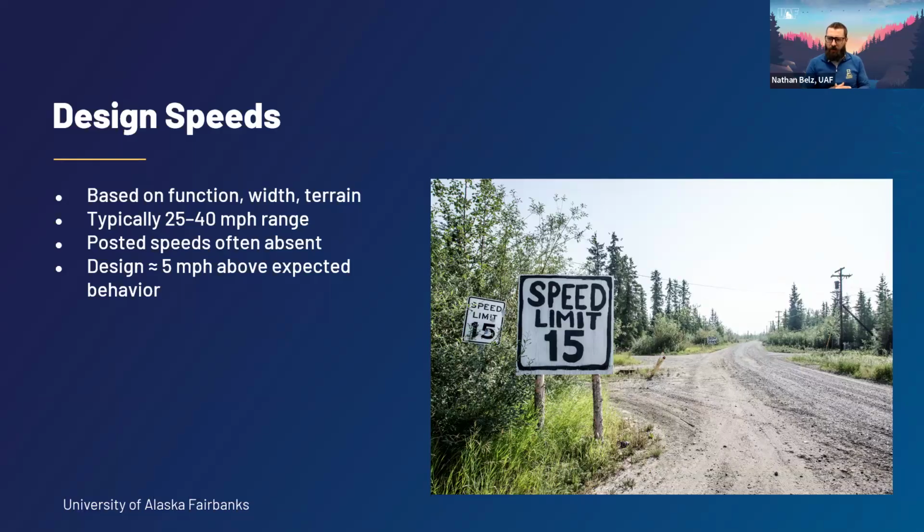So as Billy noted, really thinking about function, so the non-core versus the core road, which will drive how wide a typical roadway will be. But what we've done here is to restrict the design speeds down to 40 miles an hour and under, where then your posted speed would be about 5 miles an hour under that, with the core and residential streets being a design speed of 25, which keeps the posted speed at 20.